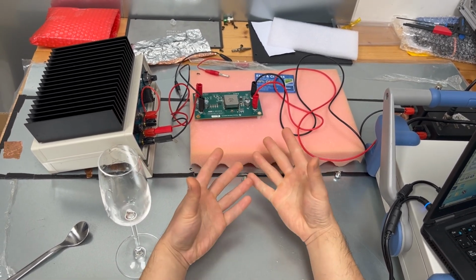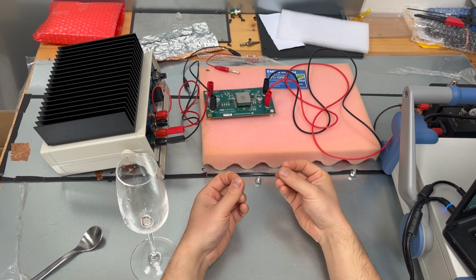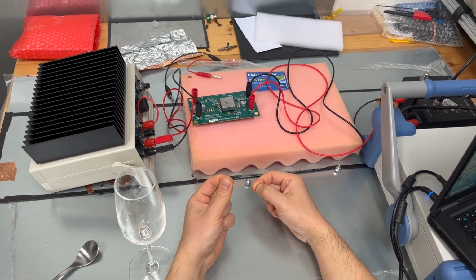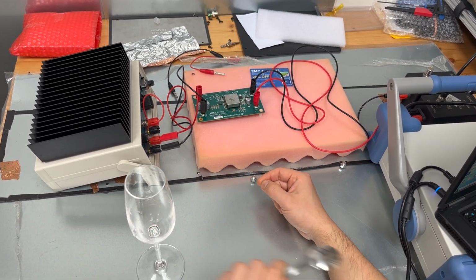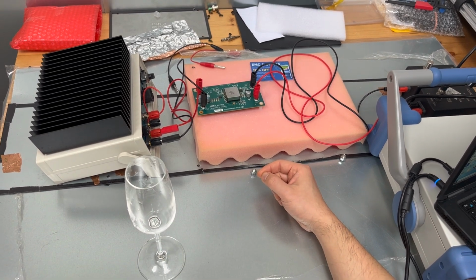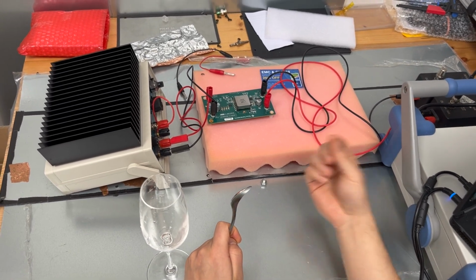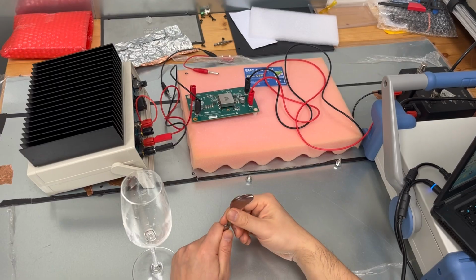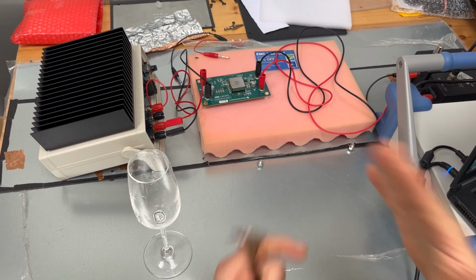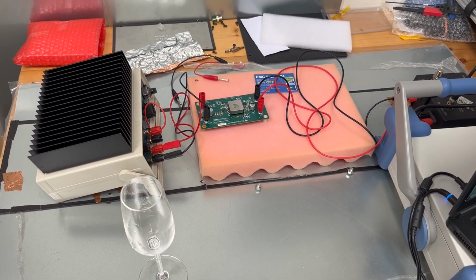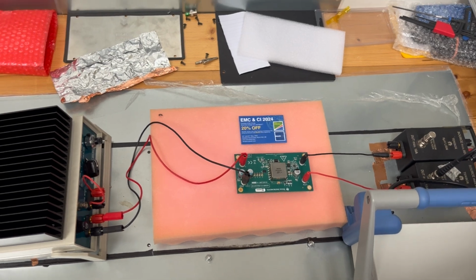Now next is, how are we going to hit the circuit with energy? Well, in this case, it is the switching device. And in this case particularly, it's not really the switching frequency that matters, right? Similar to the phenomenon that we hit the glass, it's really how hard you hit it. So how hard we switch the device really depends on the rise time of the switching event. If the rise time is small, meaning we have a hard switch, then the circuit can resonate quite efficiently.